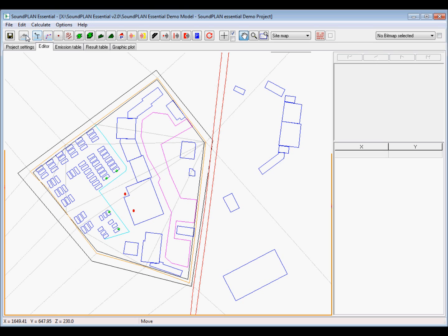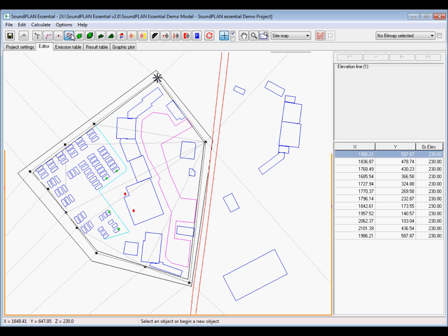In terms of this input, I entered a contour line around this block, defining it all at 230 meter elevation. So I digitized around this area. If I added, for example, an elevation line, we could go right here and put in a 230 meter elevation. That will be added later on in the digital ground model. What you see here in the background is actually the triangles.